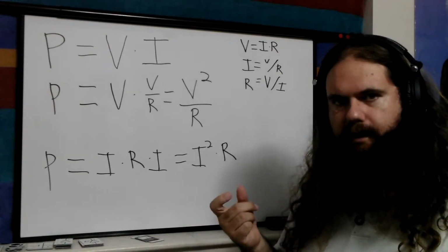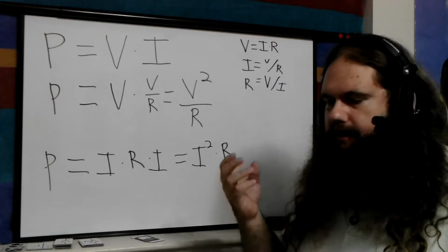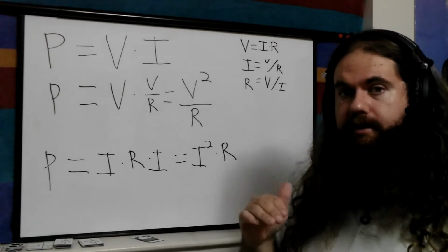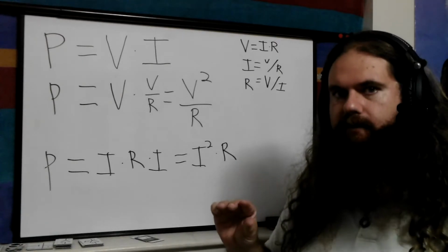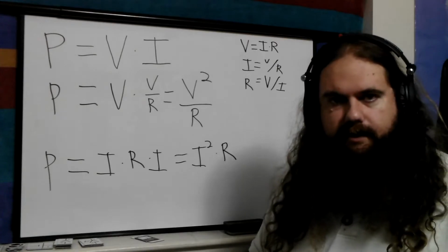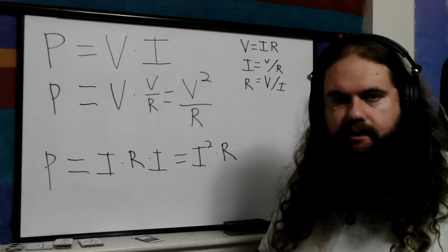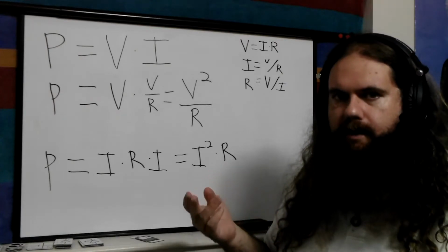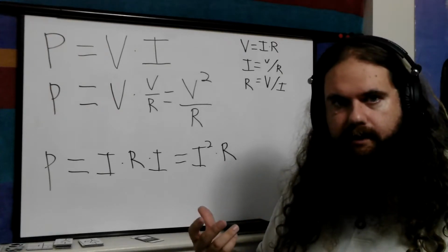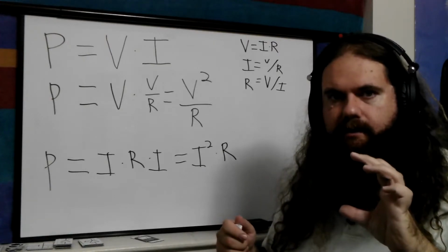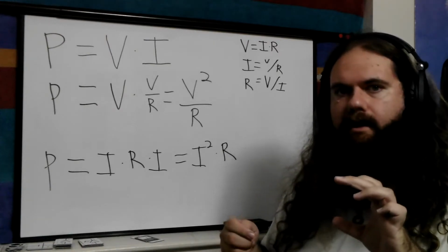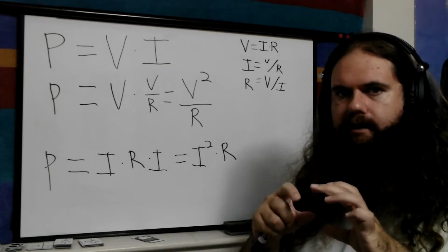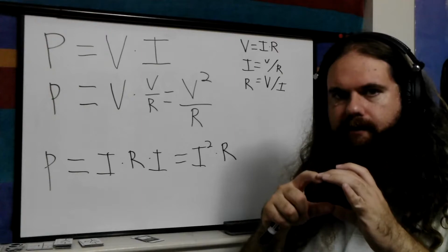So let's say we're doing part of a circuit that is mostly a control signal. It doesn't matter how much current is going through as long as it's small enough. So let's say our simple part of a circuit is the input to a transistor, sort of like an on-off switch. The amount of current is only minimally important. What matters is the voltage. So we have a voltage in, which is whether we want the transistor to be on and off. And then we have a resistor that's going to limit the current. So the resistor is dropping that whole portion of the voltage.